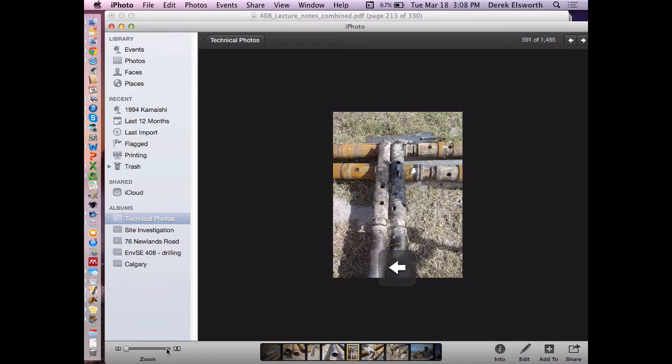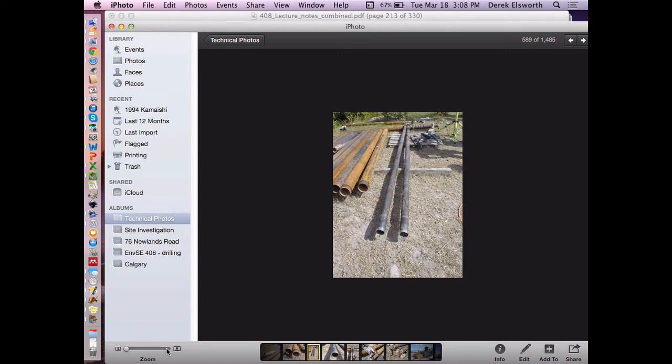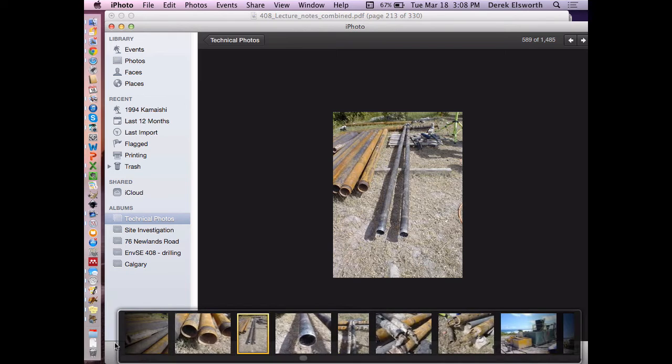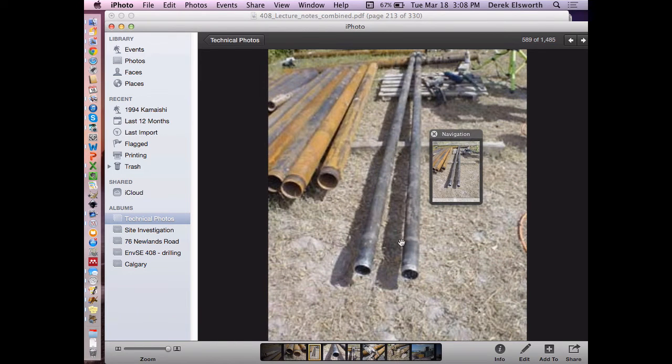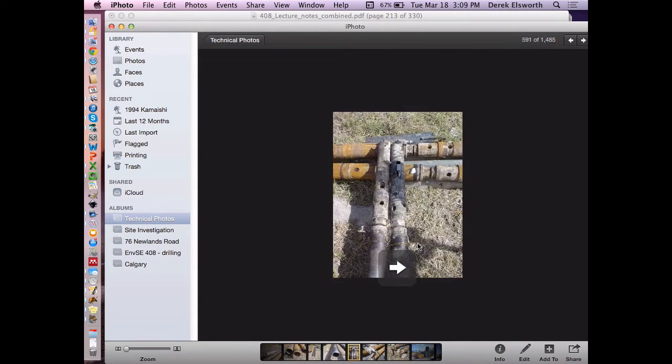You'll notice also, as I mentioned, there are two wire lines. One's down the hole, catching core. When you pull it out, you keep it out, you put a new one on, and while the other one is now drilling, you can spend your time hitting this with a hammer, sometimes, to actually get the core to come out, depending on how it's jammed. It doesn't open up in any way.